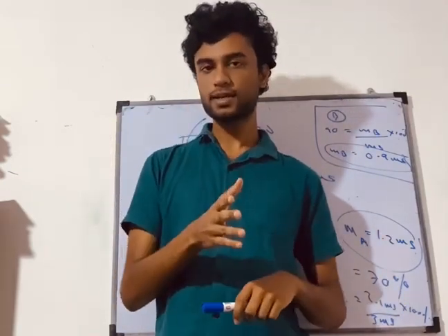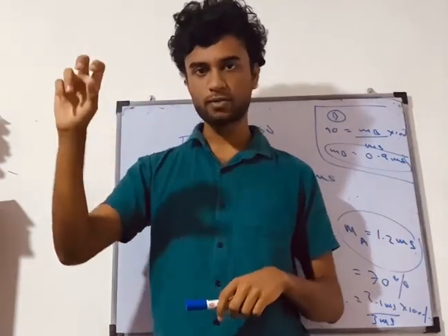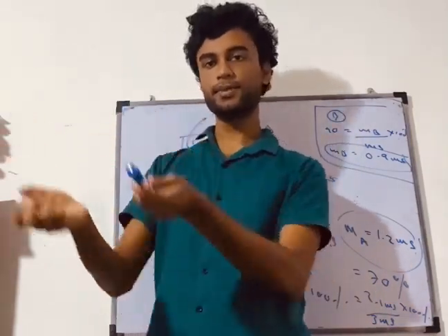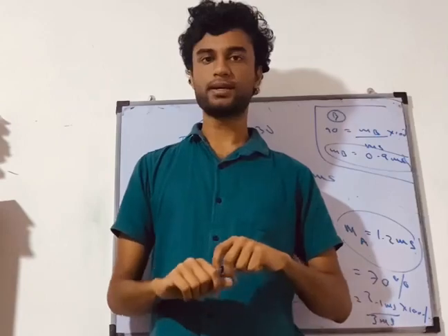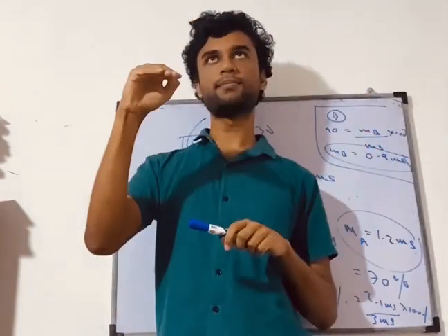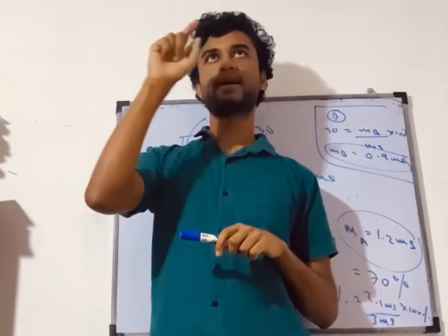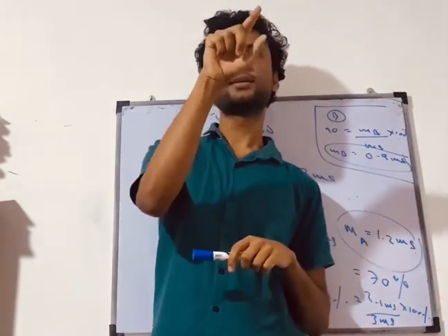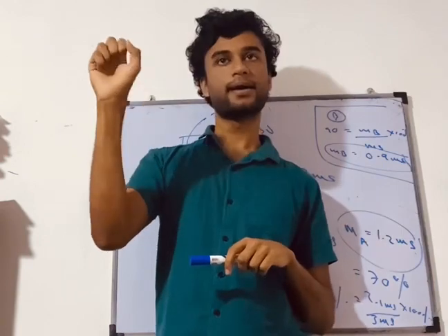So what's the relative humidity equal to? The mass that's available divided by what? Mass that I need to saturate times 100%. So mass available is going to be equal to what? Look at the equation mentally. Relative humidity is equal to m divided by ms times 100%. Then I get what? For room A, 60 is equal to what? Ma divided by what?